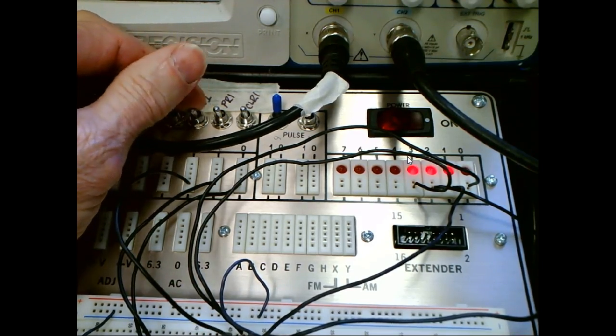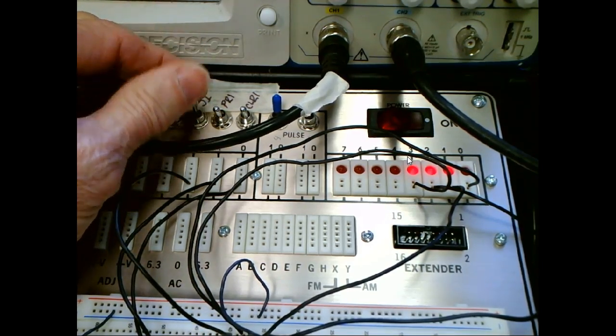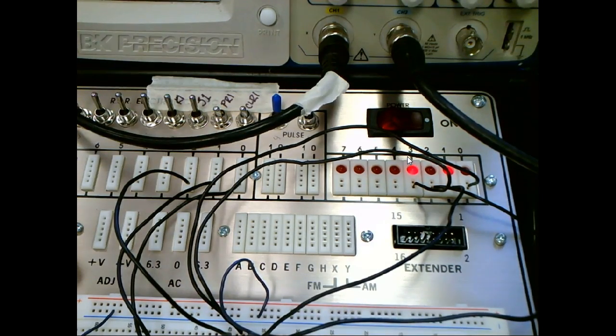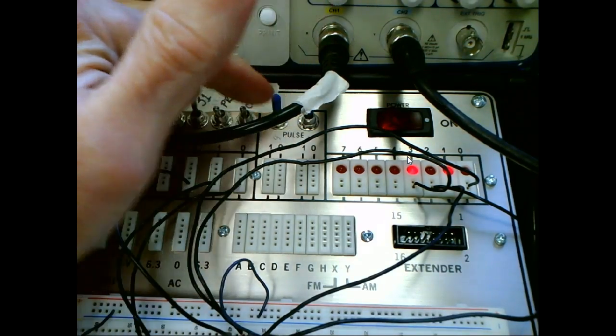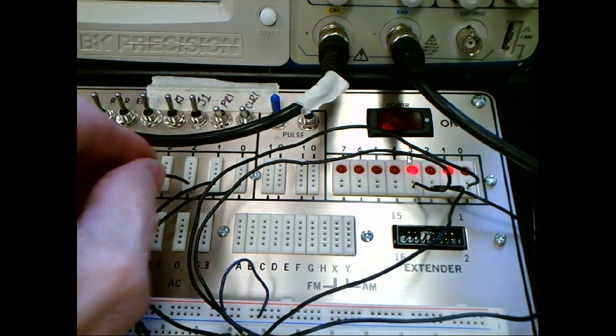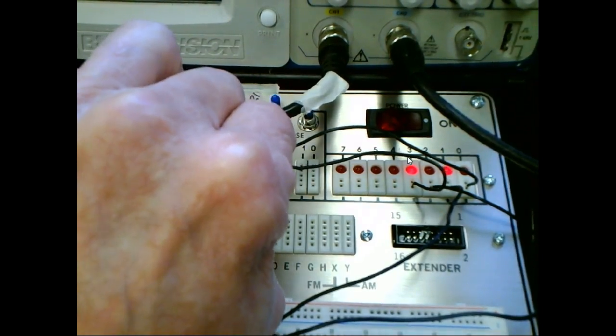Well, what's going on? I ain't counting that. What'd you say? The bounce, yeah. So when you bring a counter into these counters, these guys are fast, and it will count the bounces, right? Mechanical switches bounce. So if I've got something out there counting cans that's flying by, and I have a mechanical switch that hits that, we're going to have to debounce the circuit, right? That's the difference between these guys and these. These have that tieback NAND gate inside there, and I showed you that where it debounces.